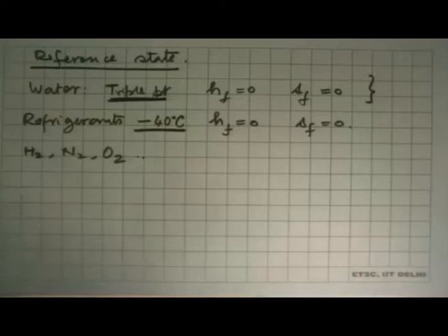Okay, here is the question. Please tell us why it is called compressed liquid. I just mentioned that it's called compressed liquid because the pressure at which the water is, is more than the saturation pressure at that temperature. So we say it is compressed. The pressure, it has been compressed into a liquid phase. That is the reason.